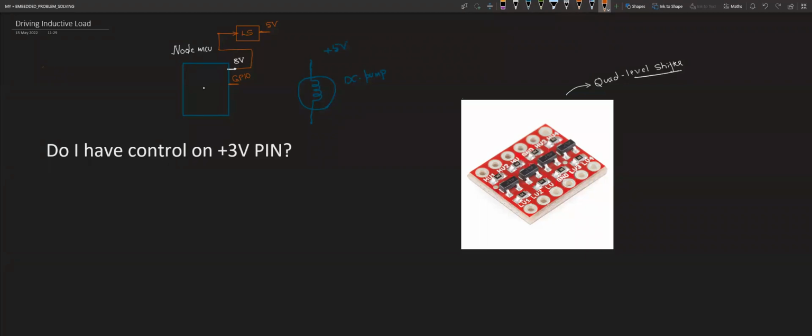So here it will again be 3 volts. I can put a level shifter, but it does not have current driving capability. So what can I do here? Anybody? Instead of a level shifter, you can use a DC to DC converter also. This is most recommended.